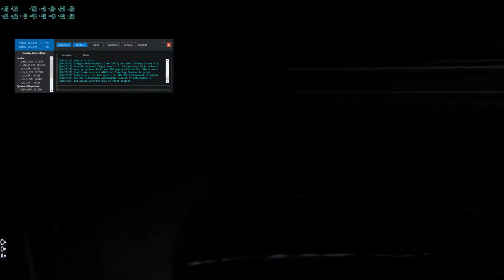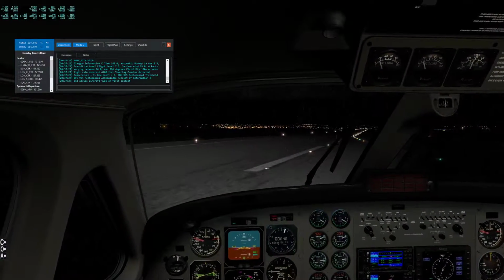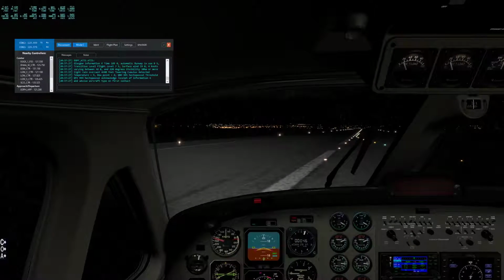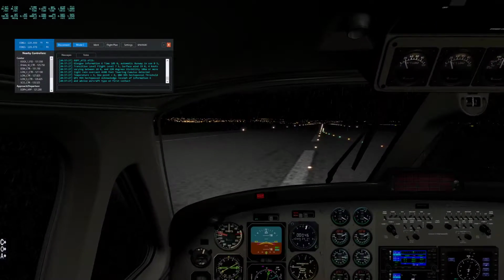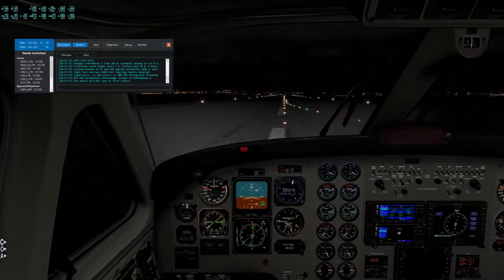Slightly thrown there because normally when you come onto a runway at the end you get the nice coloured runway end lights, and of course this is joining about 2/3 of the way along the runway, so you don't get that. But using the heading bug here just to make sure that we are actually on the runway or not on part of the taxiway.